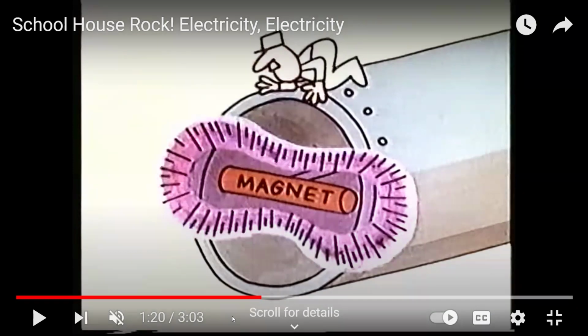So we've all seen a horseshoe magnet before. So if I take a metal hanger and a horseshoe magnet, and I just pass the metal hanger through the horseshoe magnet, there will be electricity generated at the ends of that hanger. That's literally all you need to do, a magnet and a wire, and then motion between the two. So in this case, what we've done is we've placed wires along this shaft, and inside it, or on the outside of it, I've got a powerful magnet. And so as this thing spins, those wires pass through the magnetic field.